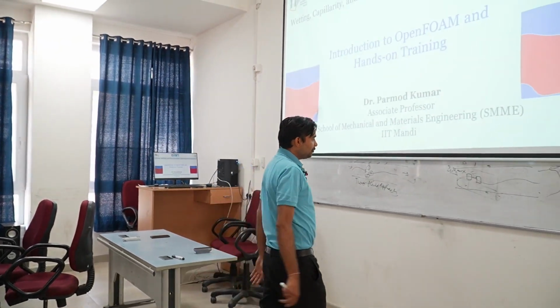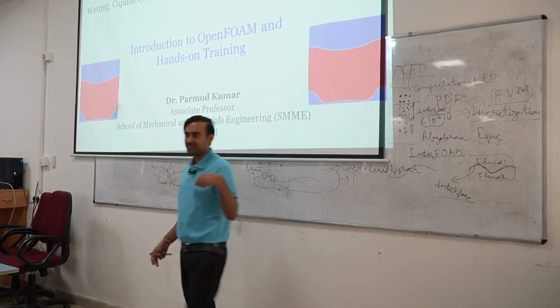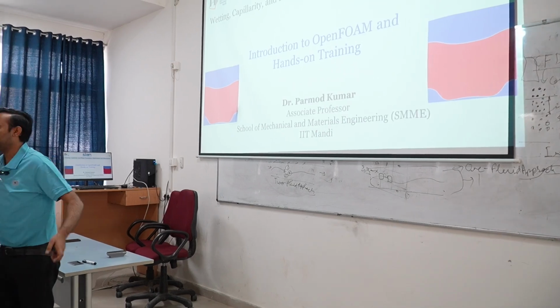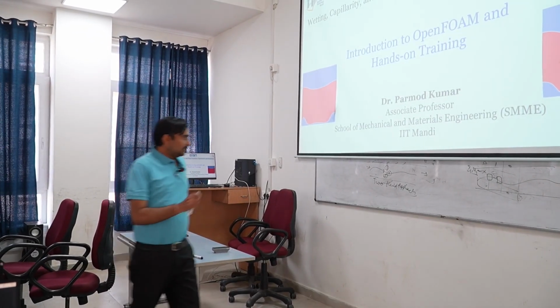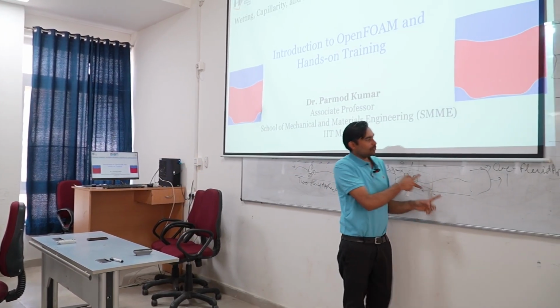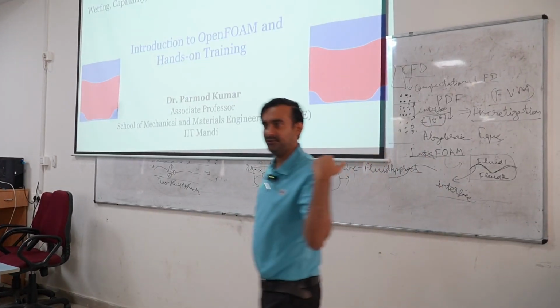Typically the force acting at the interface will be the surface tension force. So we have to include in our momentum equation, in addition to the momentum equation we use for single phase flow problems, the surface tension force. This type of approach is the one fluid approach, and it is typically implemented in the interFOAM solver.